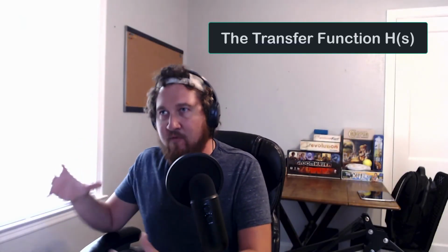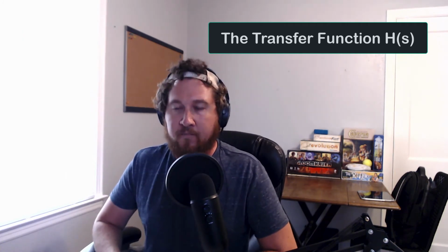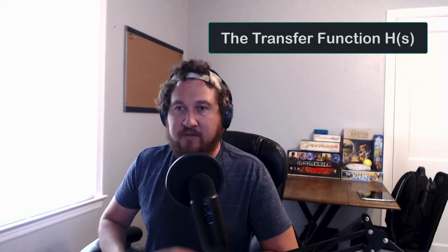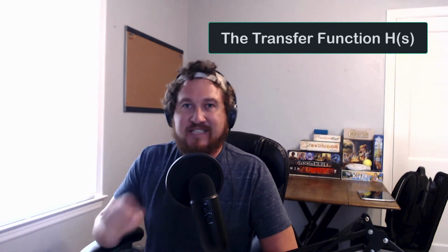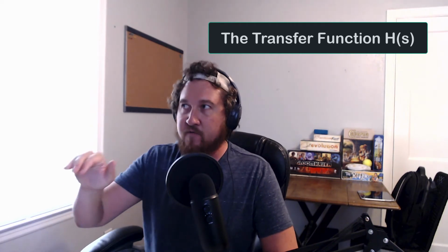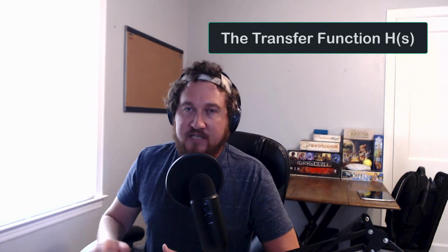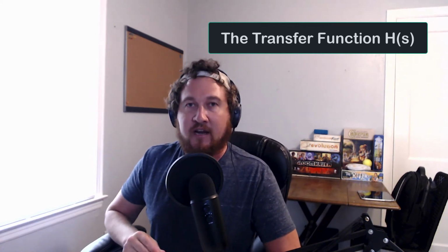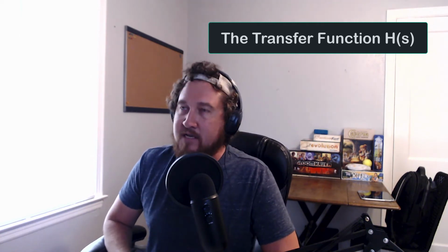Hello, and welcome to this lesson where we're going to put everything together and really hit the punchline of our discussion of the Laplace transform. In this lesson, we're going to talk about the transfer function, which basically translates into the ratio of the output signal to the input signal, specifically related to frequency. So we want to know if we put a signal of a certain frequency in, what happens to the signal coming out. And it's not hard to see where this is going to become really important when designing filters and frequency-selective amplifier circuits. But for us, filter circuits are in the next chapter.